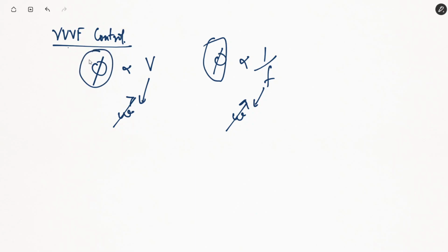इंडिविजुअली अगर हम बात करें, अगर हम वोल्टेज कंट्रोल खाली कर रहे हैं स्पीड कंट्रोल अचीव करने के लिए, आपका फ्लक्स भी वैरी हो रहा है एंड फ्लक्स इज डायरेक्टली प्रोपोर्शनल टू वोल्टेज. So if you are increasing voltage, your flux will increase, and increasing voltage also means increasing the speed of the induction motor. Or if you are going for frequency control, if you are increasing frequency, your speed will increase. But if you are increasing frequency, simultaneously your flux will decrease. Flux is inversely proportional to the frequency of supply voltage. ठीक है? This is supply voltage, this is supply frequency.